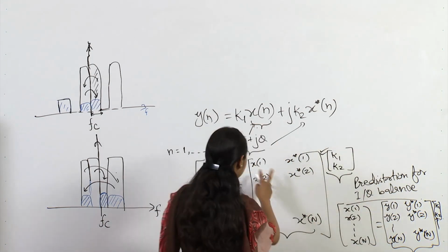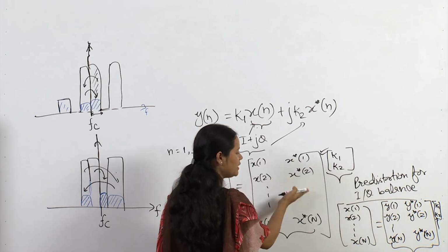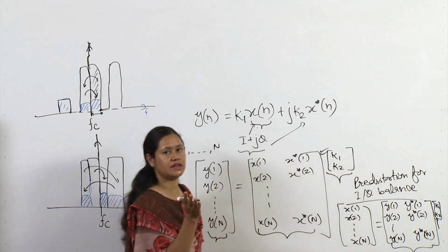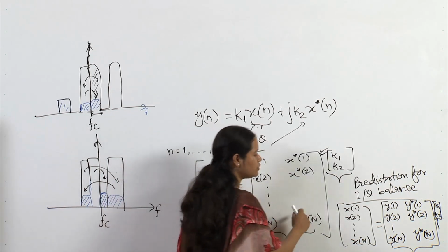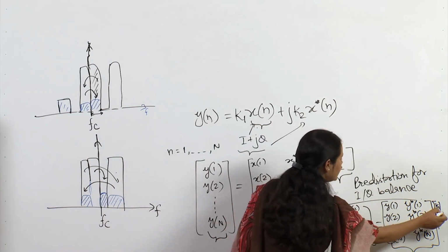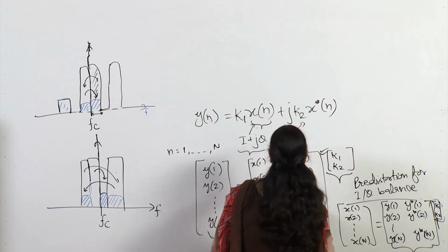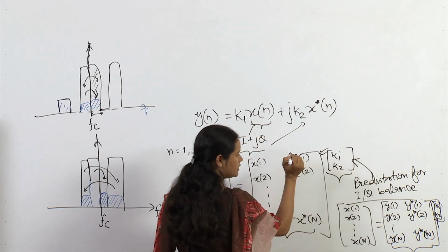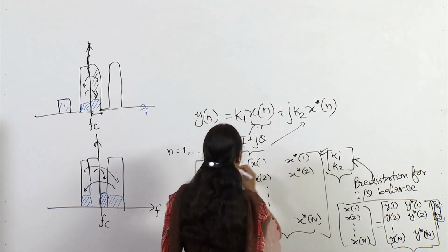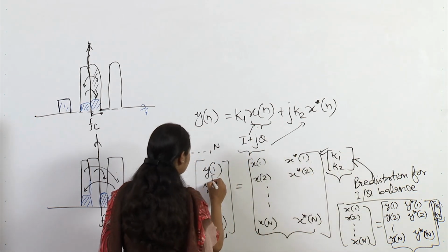So, we have swapped the input by output, output by input, because the modulator is not giving you any gain. In the power amplifier case you had gain which you removed, in this case you do not have to worry about that. So, when you find these coefficients, you can apply them in the actual path for the original data, and this y will be y PD here.